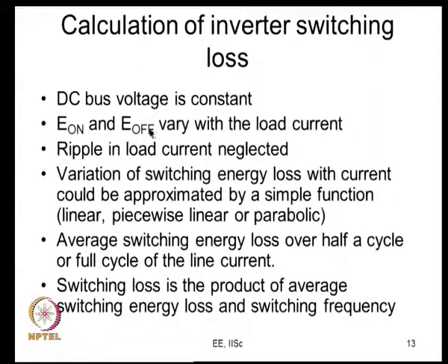Then you have this E on and E off, which are available in the data sheets, and sometimes they could have been measured, as I was just talking to you a while back. So, these E on and E off vary with the load current, you can say roughly proportional to the load current.